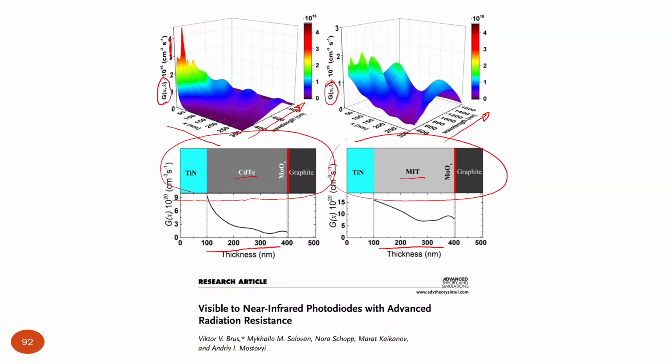So you see that for instance, for this cadmium telluride, most of the photo-generated charge carriers are created somewhere close to the surface, and not much is going on in the volume, while here, because of interference effects in this mercury indium telluride, it's a bit more transparent than cadmium telluride, less absorbing. So we have a distributed generation rate within the active layer. Obviously if we care about one wavelength, we deal with one wavelength. If we care about all wavelengths, the whole spectrum, then we can integrate it and get this generation rate as a function of position x only, because we already integrated over all wavelengths.